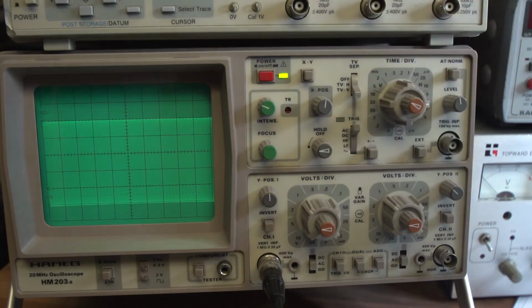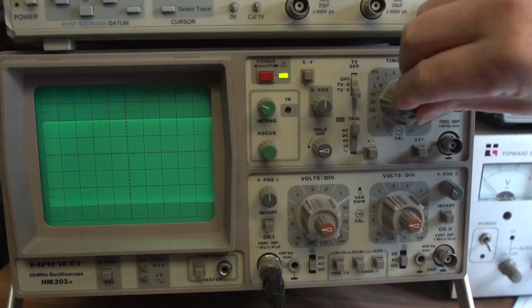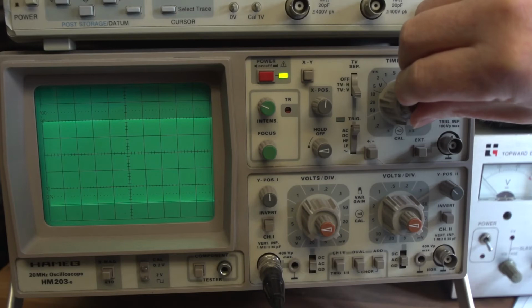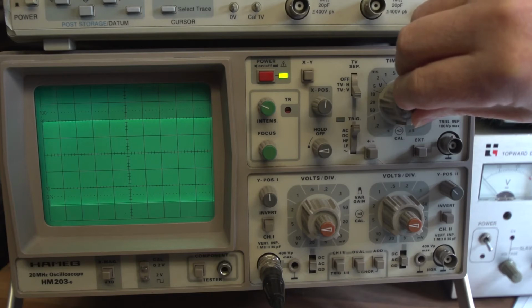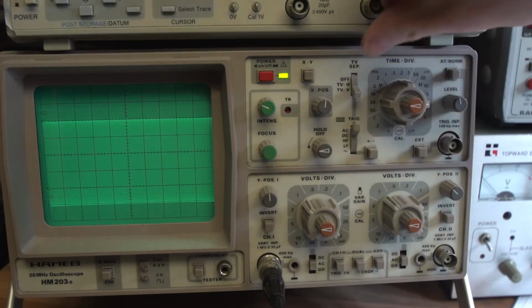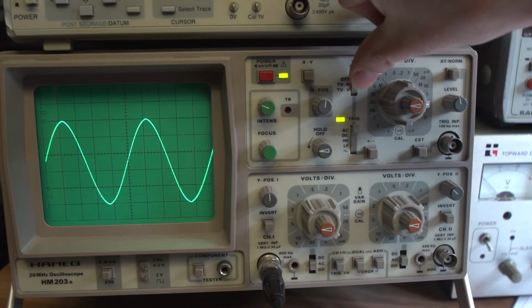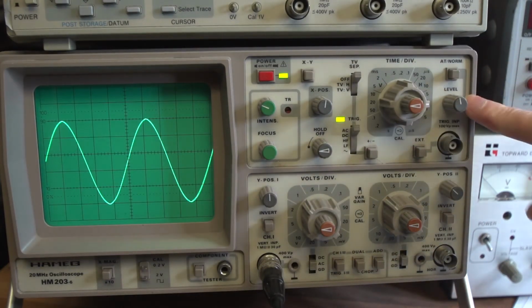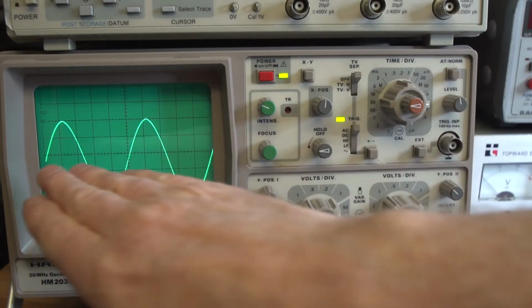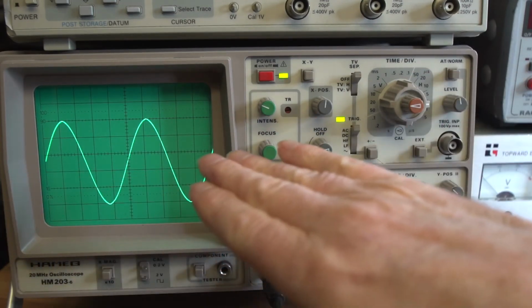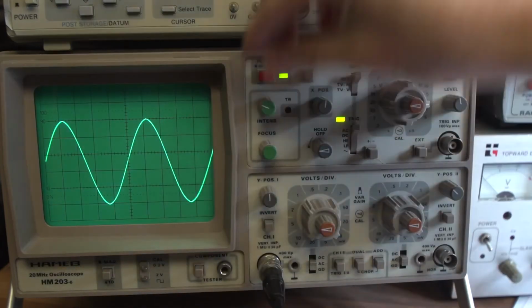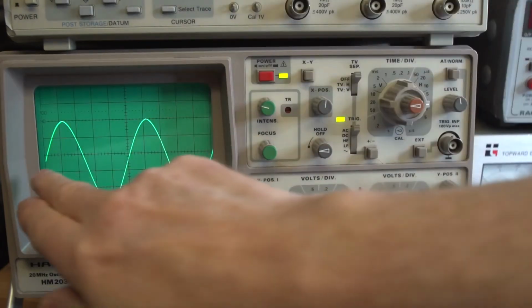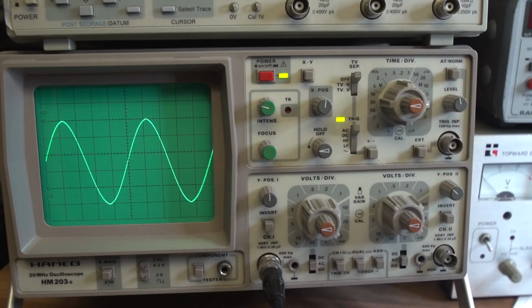true waveform at all. That's not showing us a sine wave. We don't actually know what the waveform really looks like. We've got some nice interesting patterns to look at, but it's not really giving us any information at all. It's not triggered. Put the trigger back on, and there it is, completely locked solid. So triggering is vital if you want to show a stable image, so then you can actually determine what it is that you're looking at, and then you can do your time and your amplitude measurements.